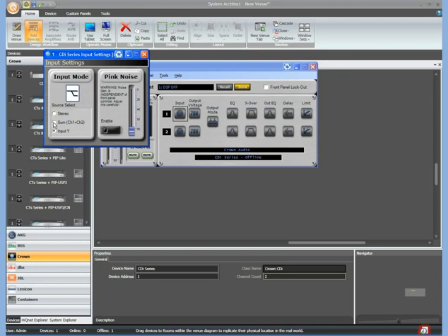For most uses in an outdoor system, we recommend sum so that we can get the same signal at all the speakers for best coverage. If you were setting up the amplifier for a true stereo application, like in a house, stereo would be the correct way, and it would be also the default when the amplifier is first turned on.